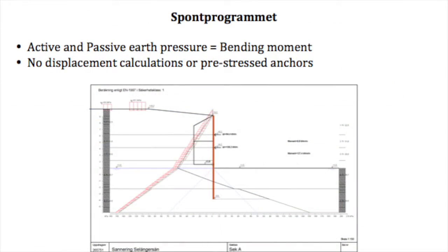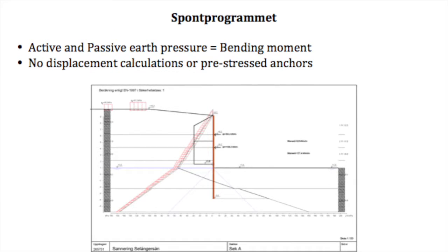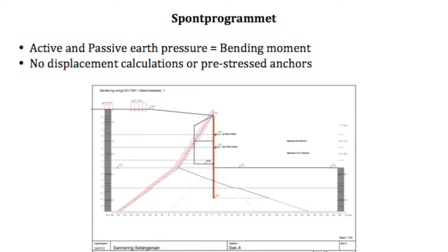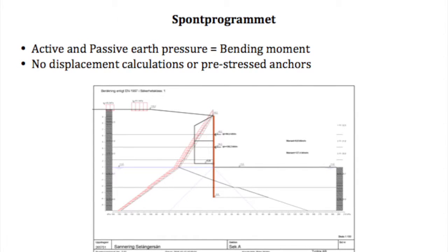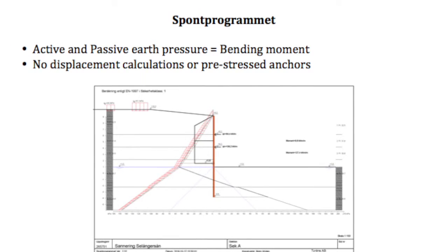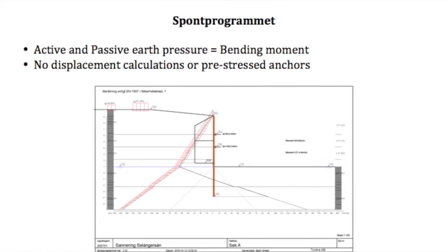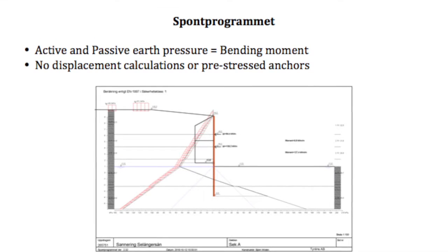The Swedish computer software ScreenCast is designed to make sheet pile wall calculations faster. The software is using the same type of calculations as when you hand calculate earth pressures along a sheet pile wall in a 2D case, and the output from the program can give you the design value of the bending moment for the sheet pile wall.